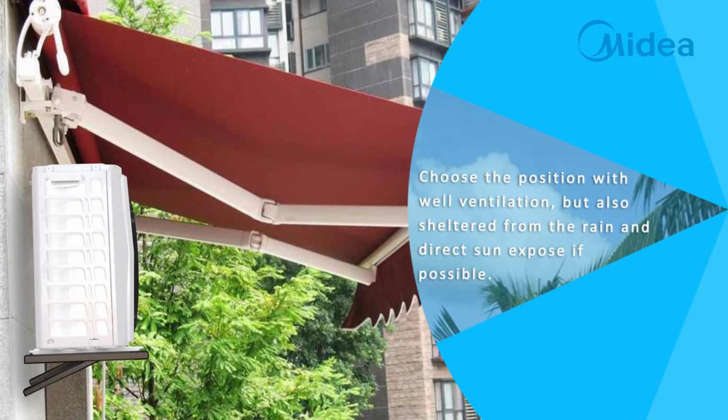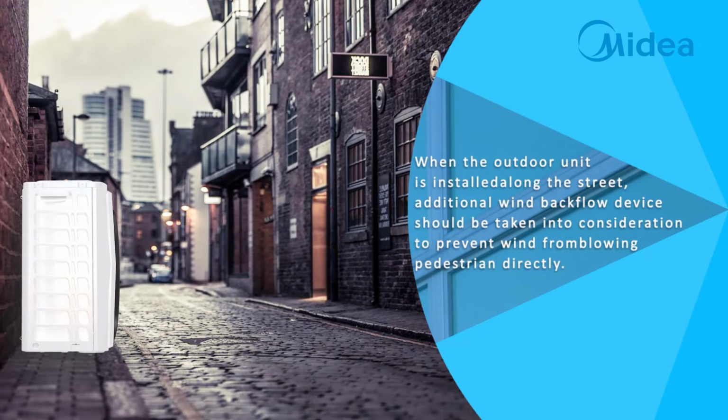Choose the position with good ventilation, but also sheltered from the rain and direct sun, if possible. When the outdoor unit is installed along the street, additional wind backflow device should be taken into consideration to prevent wind from blowing pedestrian directly.